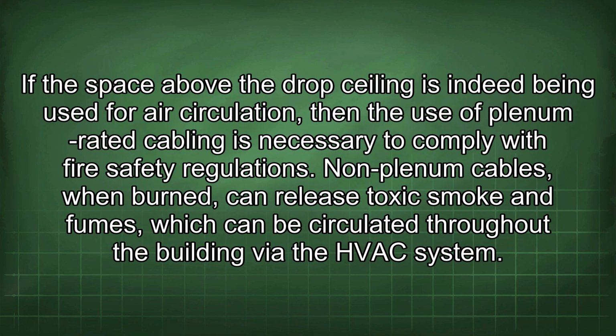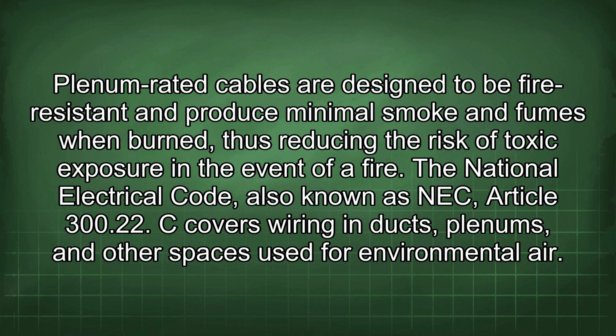If the space above the drop ceiling is indeed being used for air circulation, then the use of plenum-rated cabling is necessary to comply with fire safety regulations. Non-plenum cables, when burned, can release toxic smoke and fumes, which can be circulated throughout the building via the HVAC system. Plenum-rated cables are designed to be fire-resistant and produce minimal smoke and fumes when burned, thus reducing the risk of toxic exposure in the event of a fire.